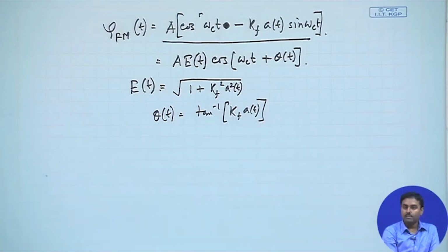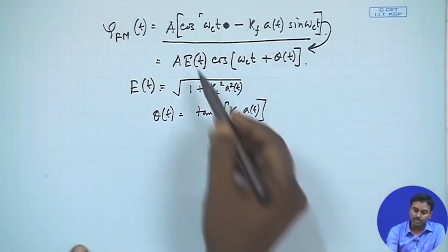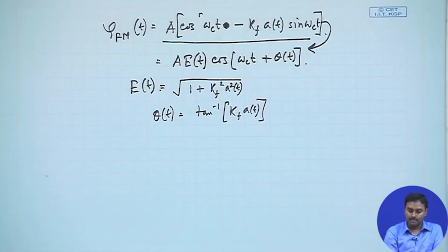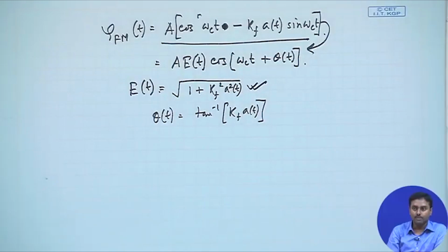So, this particular representation we already know. Okay. So, from here to here, if we wish to represent, immediately E(t) and theta(t) can be represented as this. In FM, what we expected was something like A cos of some phase variation, right. So, the amplitude remains the same, whereas in the narrowband FM, of course, there is a variation with respect to t of the amplitude.